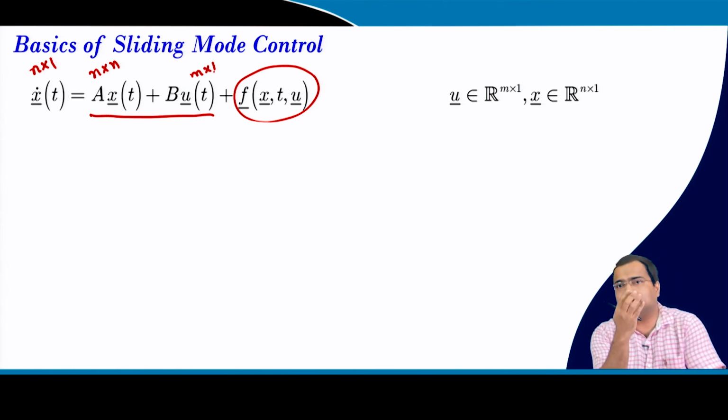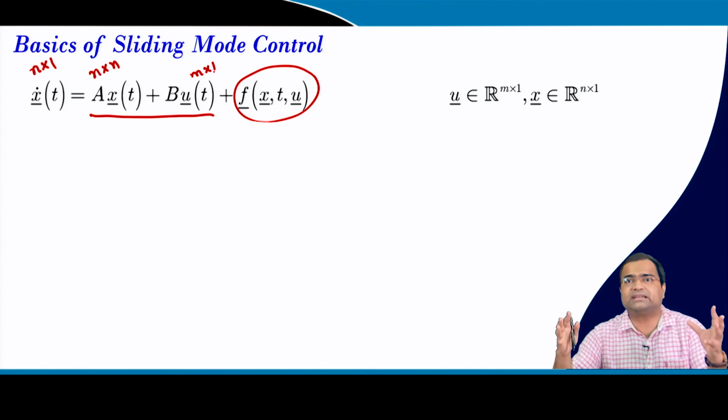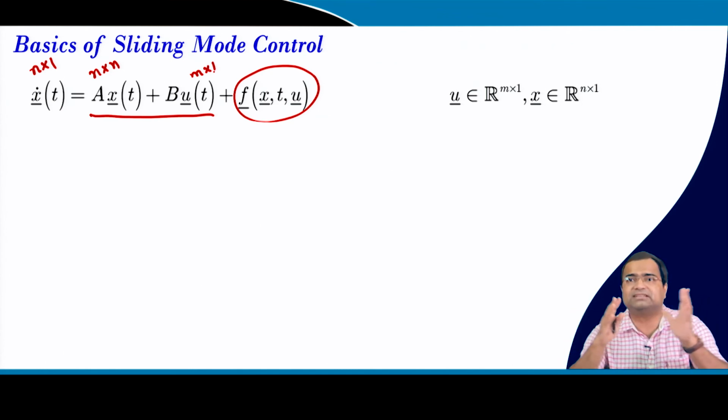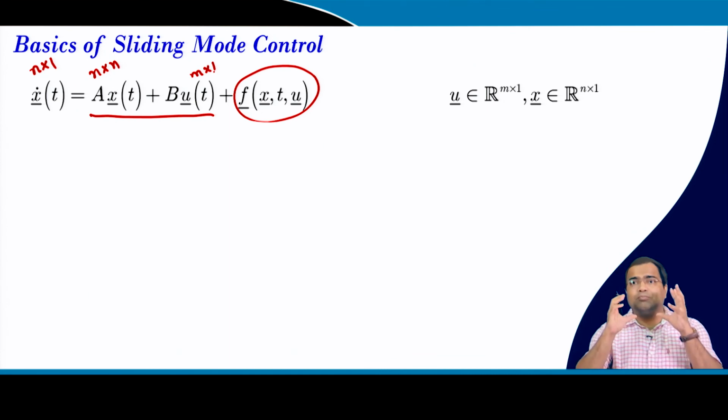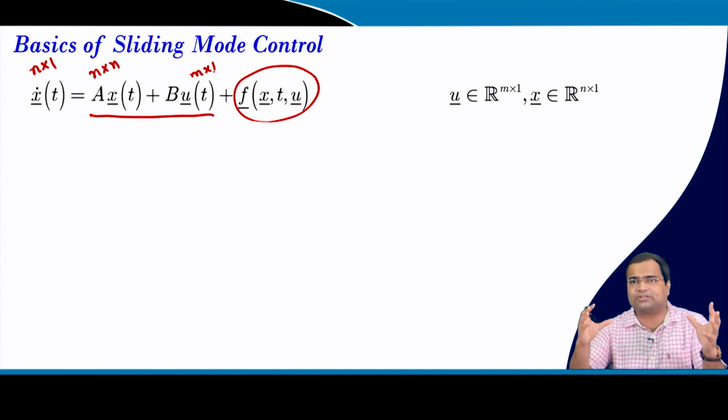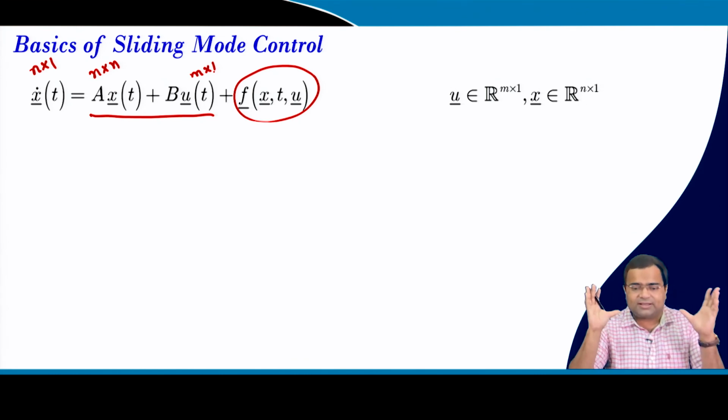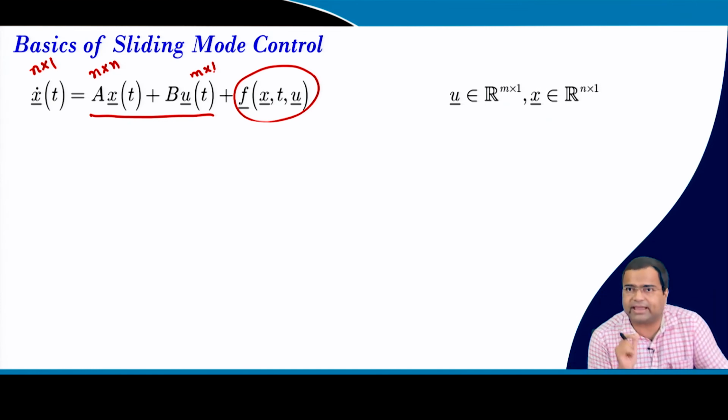But suppose you put another DC motor at the knee as well as the shoulder, then you can effectively control the movement of the hand. But we can also place a few more actuators in order to even more precisely control in different directions with a certain objective of an optimization problem or trajectory shaping problem. So, we can sometimes have more inputs in order to meet certain optimization criteria. But the penalty is that with more actuators we have to pay more, right. So, that also we need to take into account.